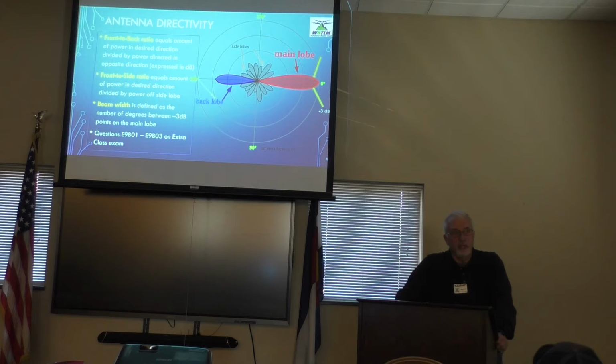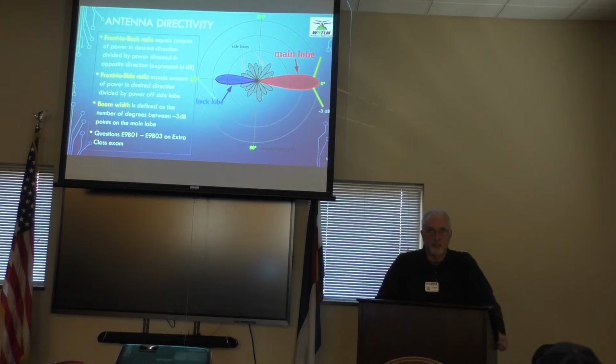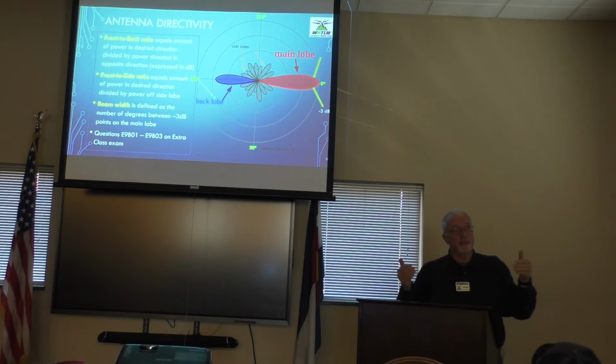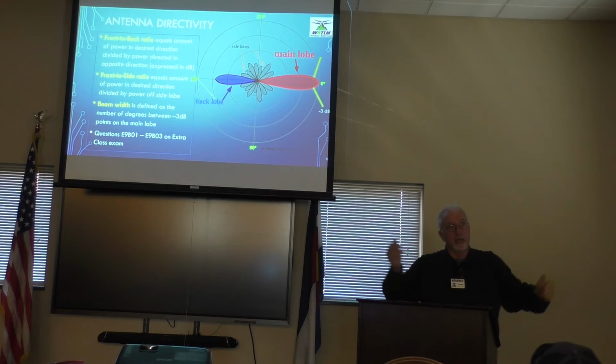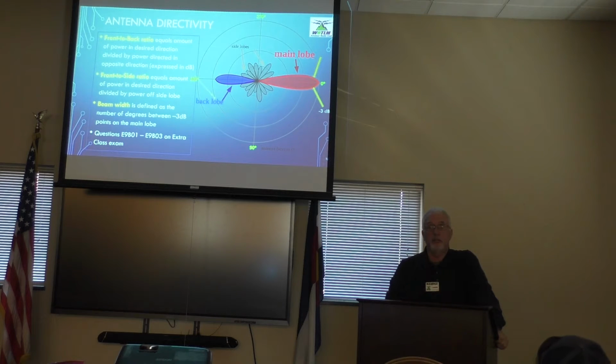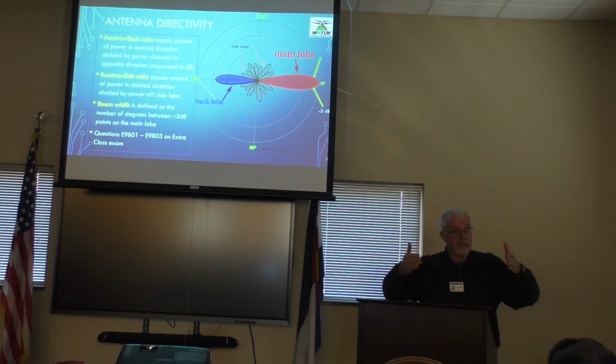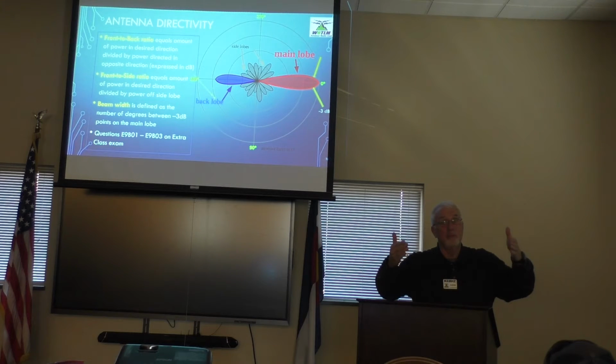So the TV antennas in the VHF range are typically not Yagi antennas, even though they look like it. Well, kind of. They're log periodics, is what the reference is, because you get more of a V shape from those, which has the effect of making the antenna more broadband. Oh, okay, so it's already trying to do that. So it's trying, and that TV antenna wasn't designed to be broadband in the ham band, but it's close enough